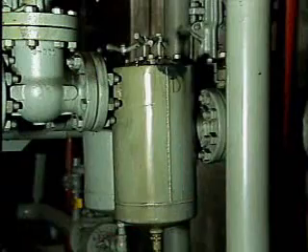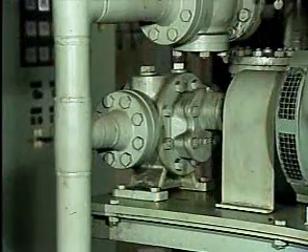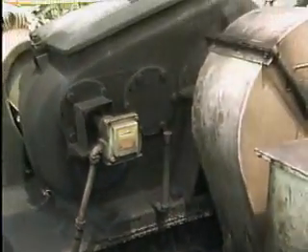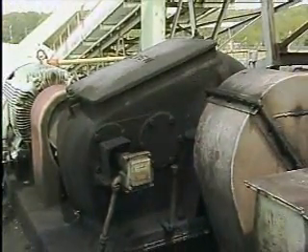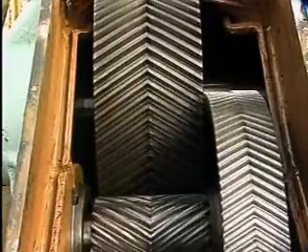Insufficient lubrication can be a result of clogged filters, clogged or improperly adjusted spray nozzles, or the improper operation of the lubricating system. Also, lubricant can be lost from a gearbox through a blown seal or a leaking joint. As you might guess, a problem that develops in a gear set's lubrication system may end up damaging the gears. Now, depending on the load in a particular gear set, this damage could occur almost immediately, or it could take some time to develop.